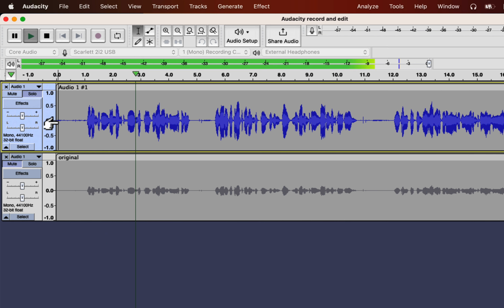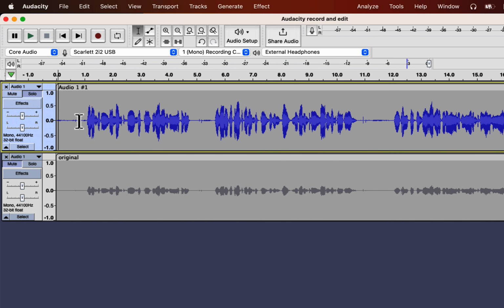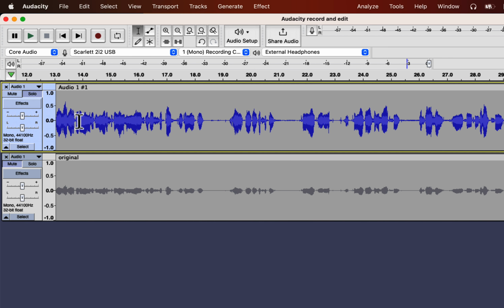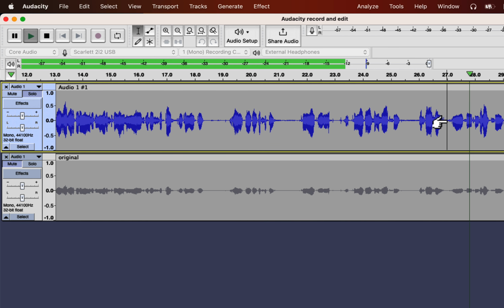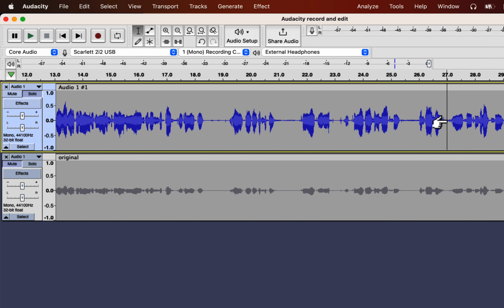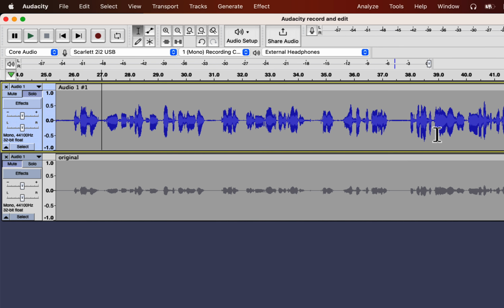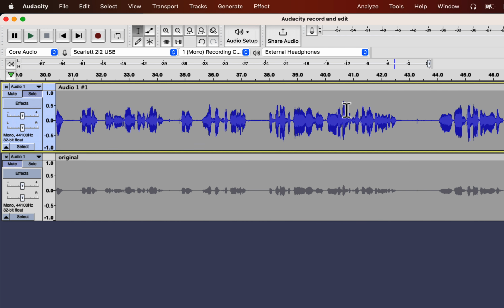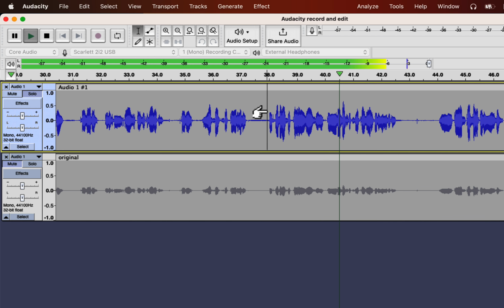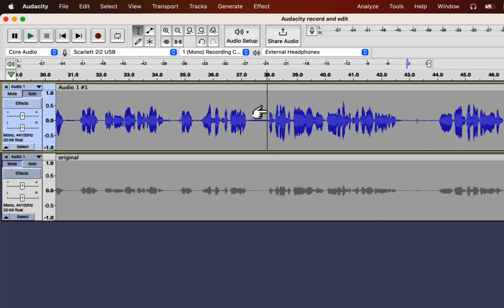Audacity is the best free software for audio editing and recording, though there are a couple of other free softwares too. You see, the audio has become louder and is not crossing -3 in the meter. Let me find a sample with a higher peak. And if you think about some paid software, it is not getting close to -3. Let me find another sample. It looks like this one has the loudest peak. But whatever software you use, you have to know the basics of audio recording and editing. So you see, it is not crossing -3 as I had normalized the peak to -3.